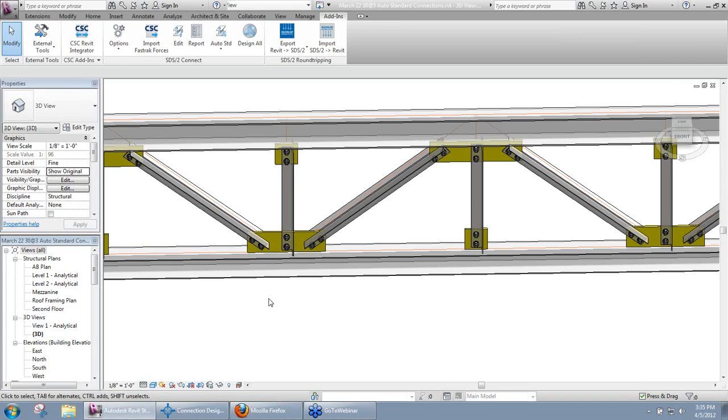But again, during connection design, we're looking at the hole size, what type of holes they are. As you saw in that shear plate connection earlier, it was telling me that slip critical bolts were required in that situation. That's because of the standard or the short slot holes that were being looked at rather than just a standard round hole. So again, we take them into account, just do not display them.